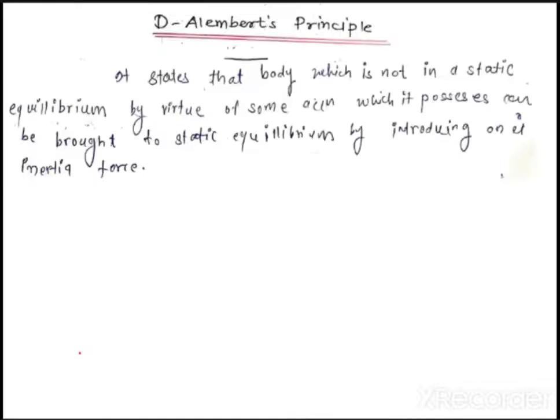Shall I move forward? Now, D'Alembert's principle. Do you know what D'Alembert's principle is? It states that a body which is not in static equilibrium by virtue of some acceleration which it possesses can be brought to static equilibrium by introducing an inertia force.